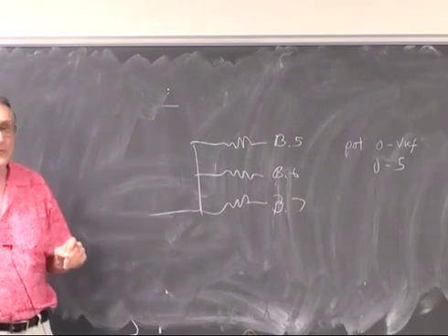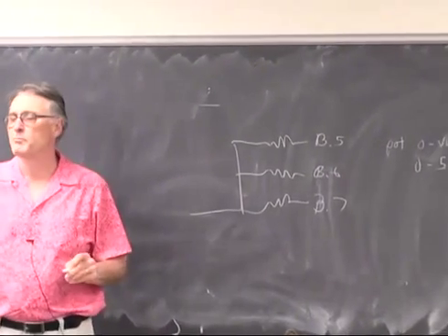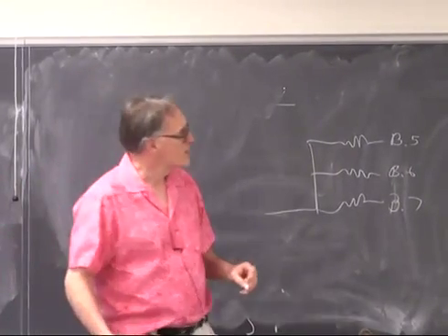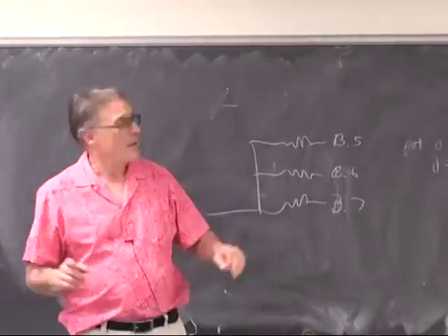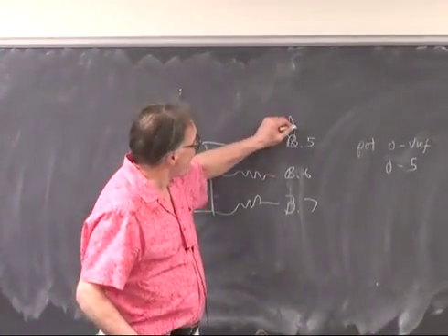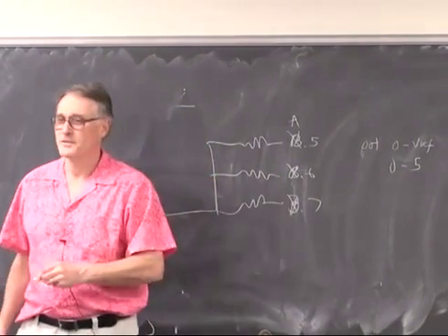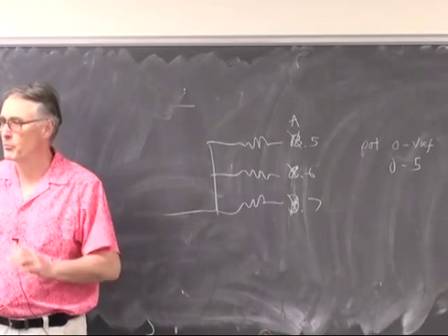The fix for this is you can do either one of two things. One is you can just pull the programmer plug off every time, but that's tedious. What I suggest, and the way I changed the documentation in the lab, is to make this A5, 6, and 7, and then it works without a problem.